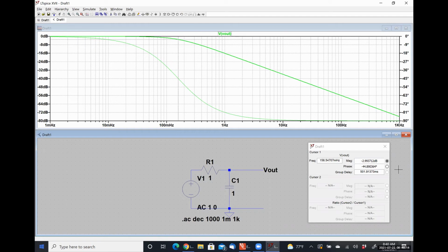So we've got to pay attention to stuff like that. If you calculate the corner frequency in radians per second, LTspice is going to give it to you in linear frequency, so you're off by a factor of 1 over 2 pi. So our mathematical description is actually describing this extraordinarily well, right?